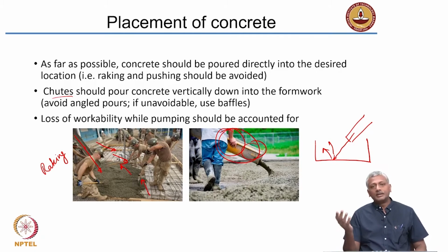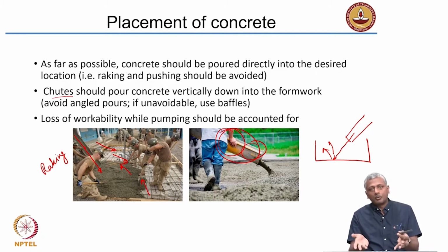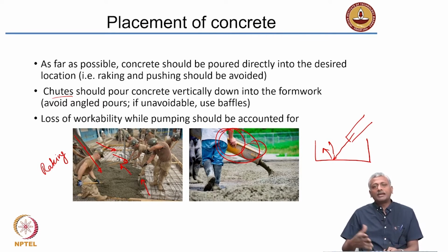For example, at the point of time of pouring, if you want a slump of 100 millimeters, you need to design the concrete for conveyance at the ground floor for nearly 150 millimeters to ensure that any losses in slump during the flow in the pipe can be avoided.